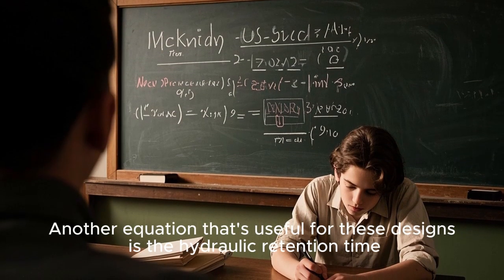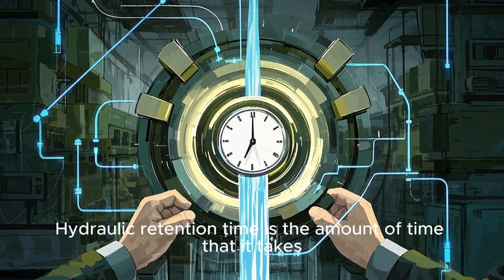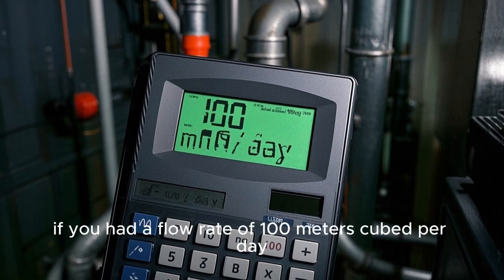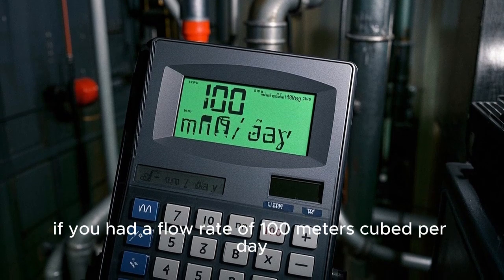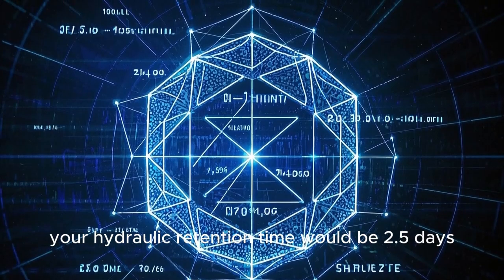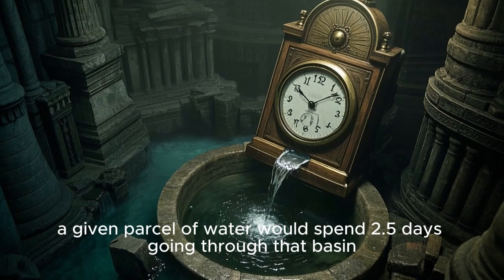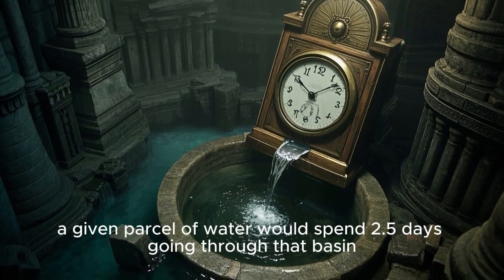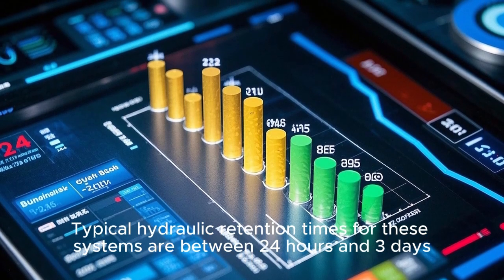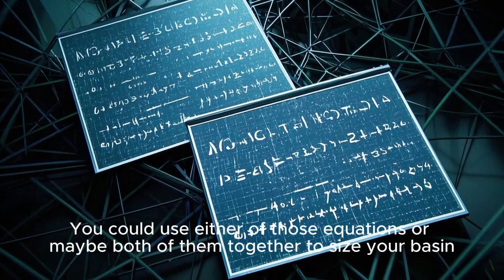Another equation that's useful for these designs is the hydraulic retention time. Hydraulic retention time is the amount of time that it takes for a given volume of water to go through the system. For example, if you had a flow rate of 100 meters cubed per day and you had a basin with a volume of 250 meters cubed, your hydraulic retention time would be 2.5 days. So that means that on average, a given parcel of water would spend 2.5 days going through that basin. Typical hydraulic retention times for these systems are between 24 hours and 3 days. You could use either of those equations, or maybe both of them together, to size your basin.